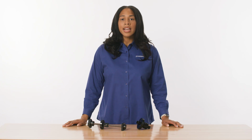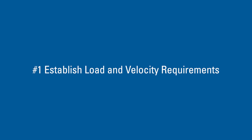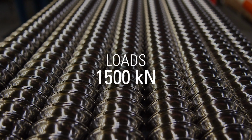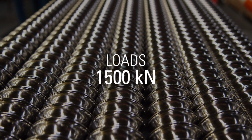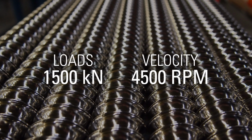So when it comes to selecting the right ball screw for your application, knowing and understanding your application's requirements is crucial. Here are some helpful steps to ensure you're on the right path. Start by defining the load and velocity requirements. Ball screws can handle high thrust loads upwards of 1,500 kilonewtons and achieve velocities up to 4,500 RPM.